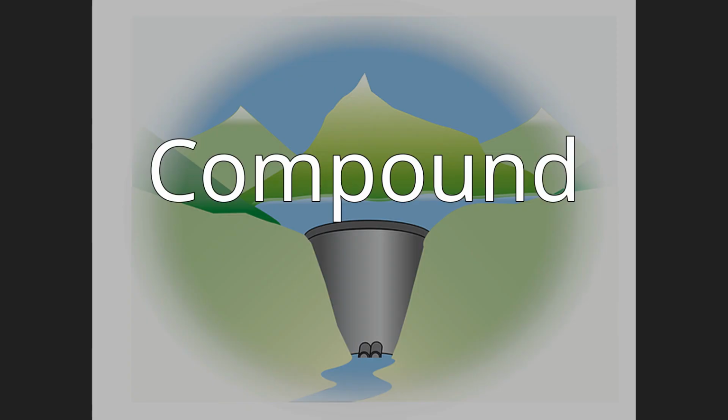Compound. A compound weir is any weir that comprises several different designs into one structure. They are commonly seen in locations where a river has multiple users who may need to bypass the structure. A common design would be one where a weir is broad-crested for much of its length, but has a section where the weir stops or is opened so that small boats and fish can traverse the structure.